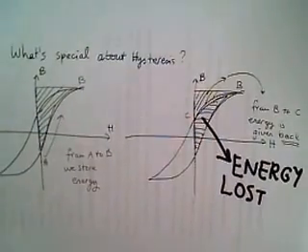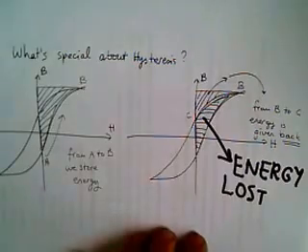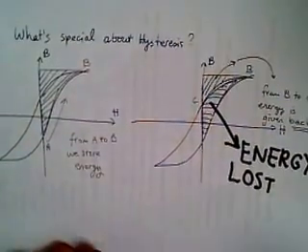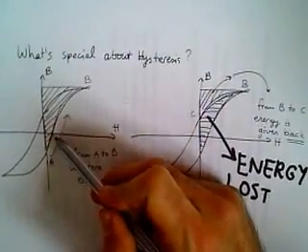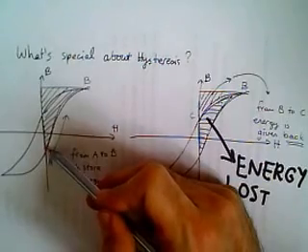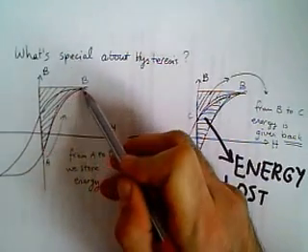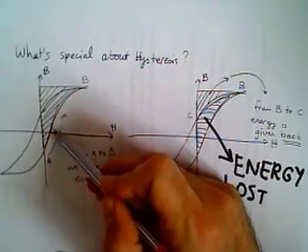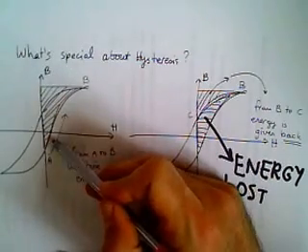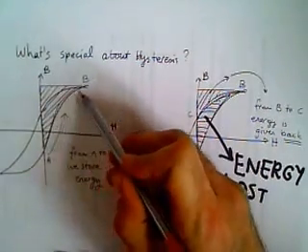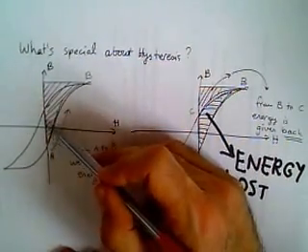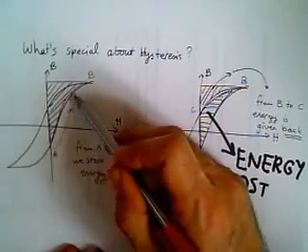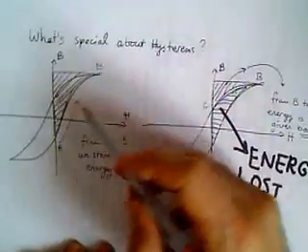Now we come to the electromagnetic stored energy concept. If a magnetic material is following a hysteresis characteristic, the area under the nonlinear curve and the vertical axis represents the stored energy within the material.